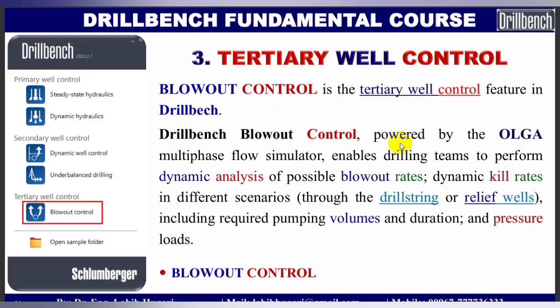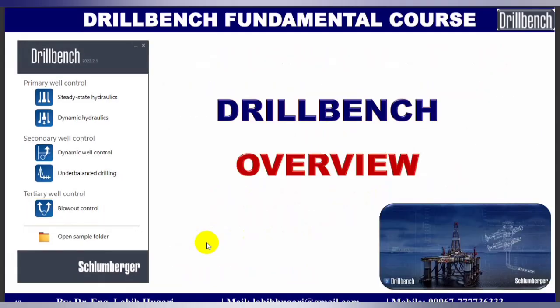Drillbench blowout control, powered by the Olga multi-phase flow simulator, enables drilling teams to perform dynamic analysis of possible blowout rates and dynamic kill rates in different scenarios through the drill string or relief wells, including required pumping volumes and duration and pressure loads. This is the blowout control.